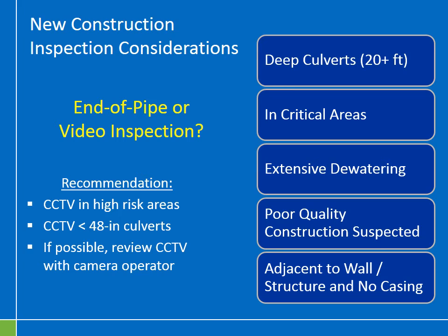Consider CCTVing when the culvert is smaller than 48 inches. Culverts smaller than 48 inches tend to get a little more difficult to climb into and do a really good visual internal inspection. So, CCTV cameras are going to be a helpful tool there.